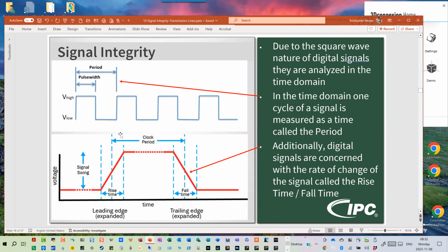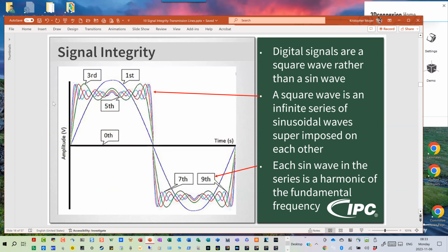So is that clear to everybody what I'm talking about here? Is that this edge rate is created by the driver pins of all of our devices. And as the silicon manufacturers keep making those devices smaller and smaller and smaller, they get faster and faster and faster. And therefore, the edge rates get faster and faster and faster, which means even running at slow clocks, the frequency content to create that sharp of an edge rate exists inside that square wave because of what we just talked about right here, the superposition, right? I only need 9 harmonics here, and I get a slow edge rate.